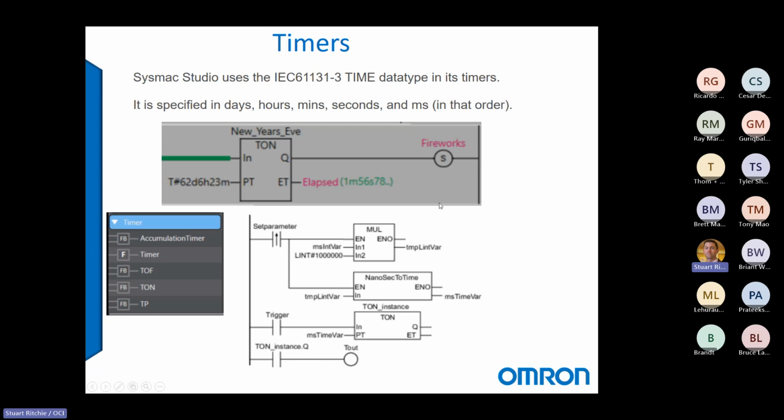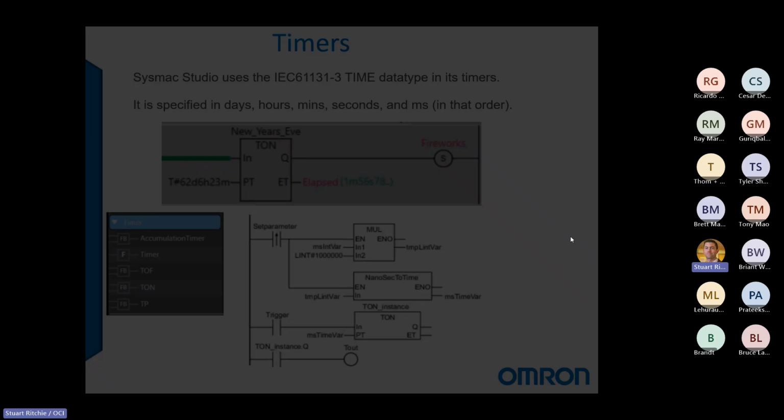Now, the time data type doesn't play well with all visualization devices like HMIs or SCADA. So sometimes you do have to do some modifications to set a timer from an HMI, for example, but all of the timer instructions or anything related to the time data type has example code on how you do that, and we have instructions to support that within Sysmac.